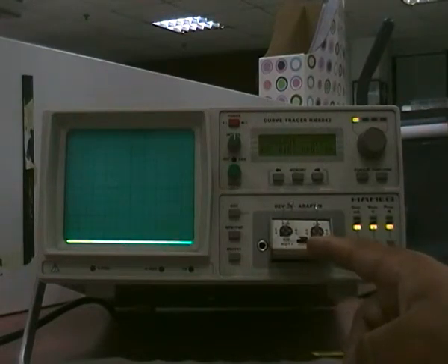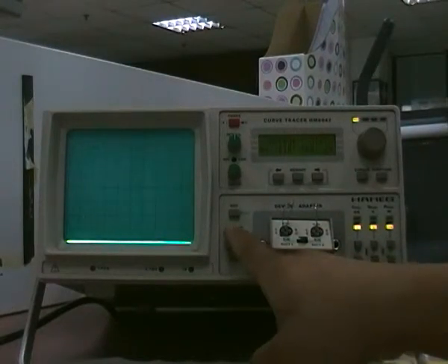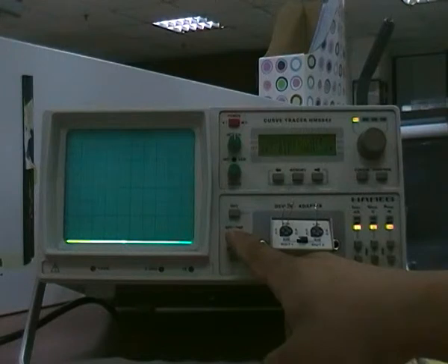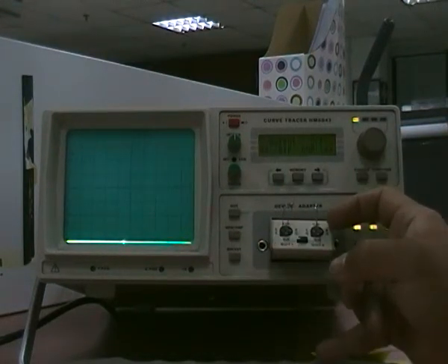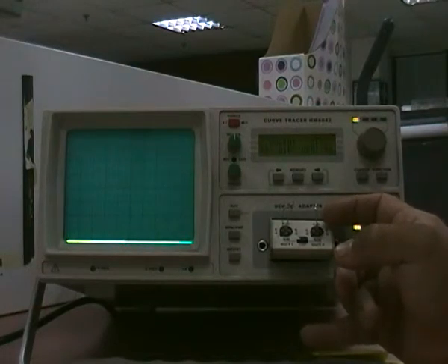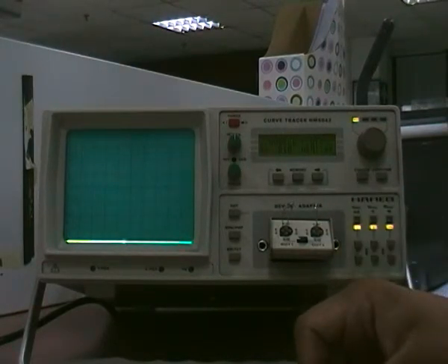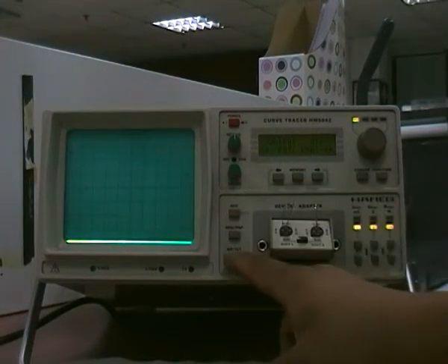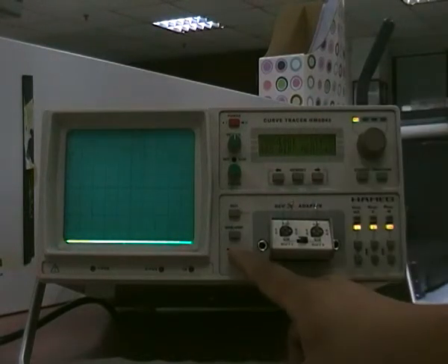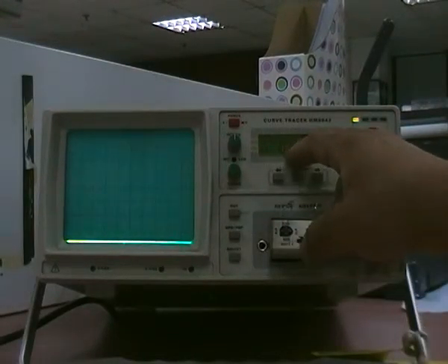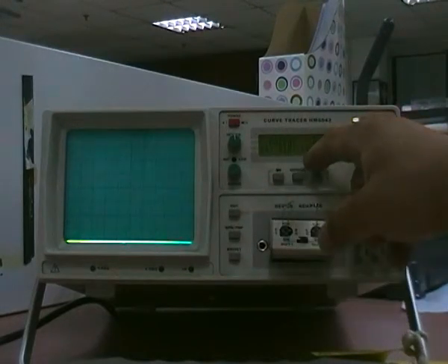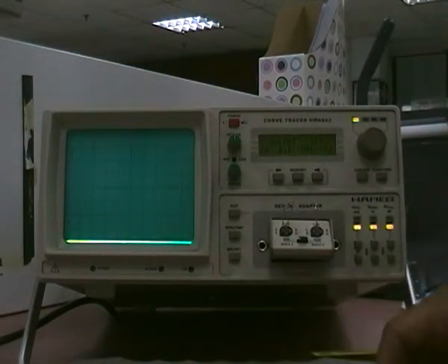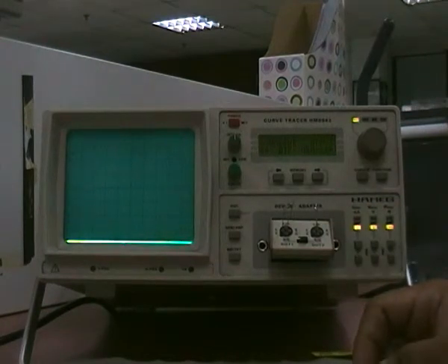Alright, I'll give you one example. This is a silicon-based diode, so I'll put it under NPN or PNP, it doesn't matter, it will be the same. If I use NPN, it means the current will flow through C to E, so that's the diode that we want to measure. This is a bipolar input, this is FET-based input, N channel, or bipolar NPN, so bipolar NPN. I know that this is a signal diode 1N914.